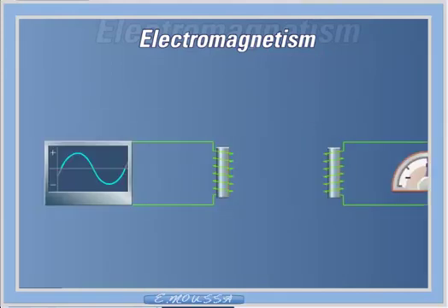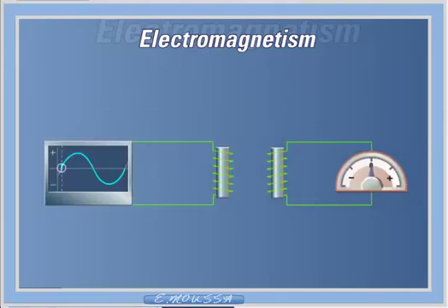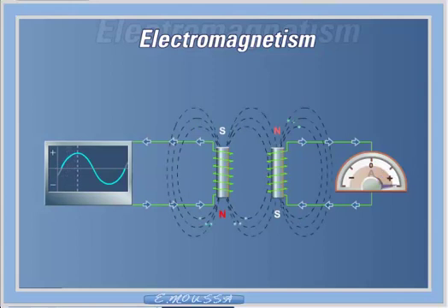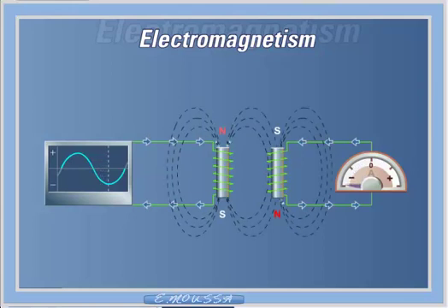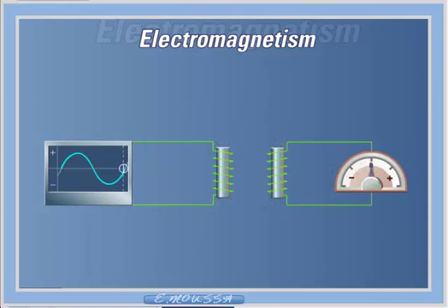If a second electromagnet is brought into close proximity of our AC excited electromagnet, the cyclic expansion and contraction of the magnetic field of the excited electromagnet will in effect be continuously cutting the conductor windings of the second electromagnet, which will induce a voltage and hence current in the non-excited coil. This induced current will create a secondary magnetic field as illustrated.